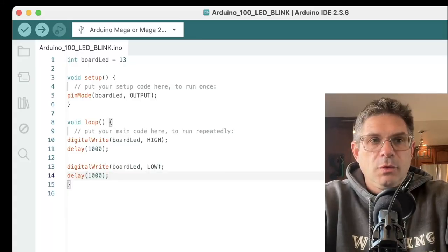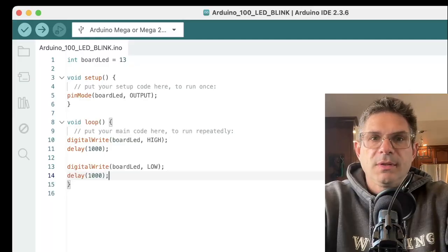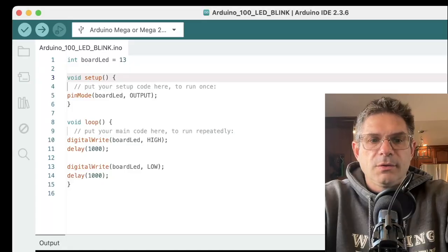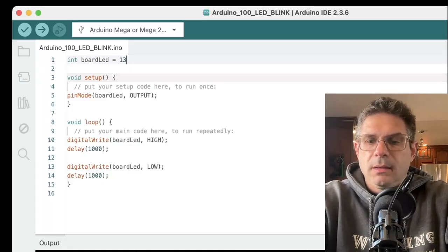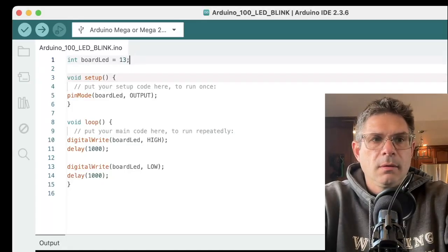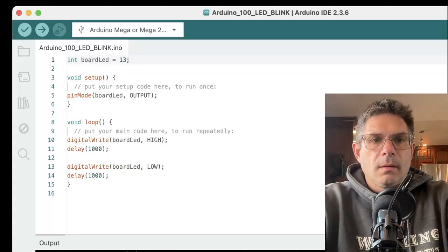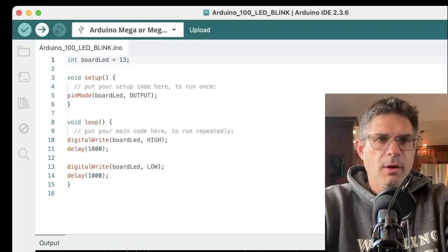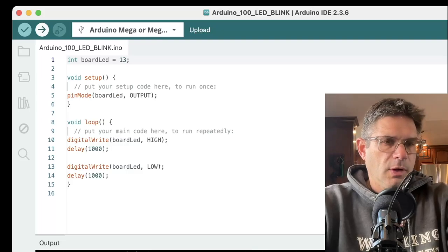We're going to do a quick save, and let's upload it to the board. I'm going to verify all my code is correct. Oh, look at this. It said I missed a semicolon. Thank you again. And we are going to select our Arduino board. Now we are uploading it to the Arduino itself.